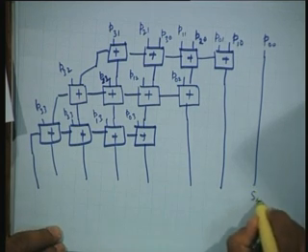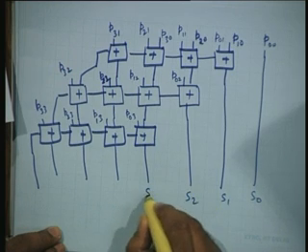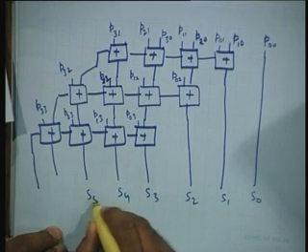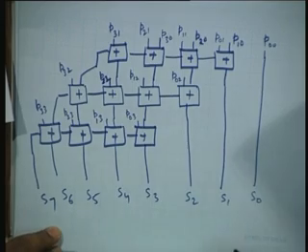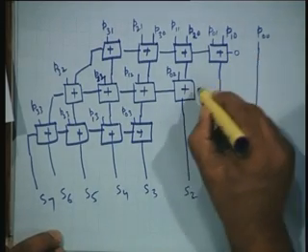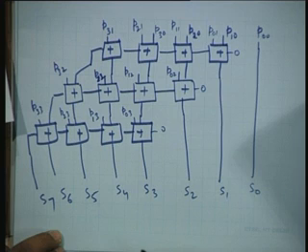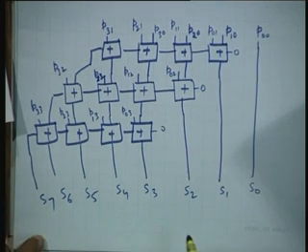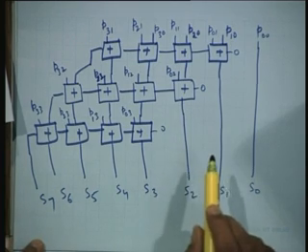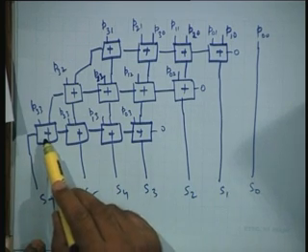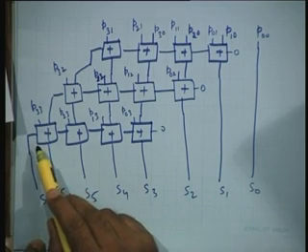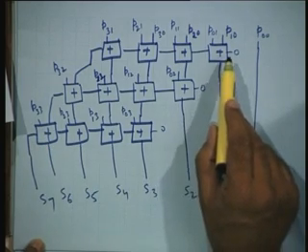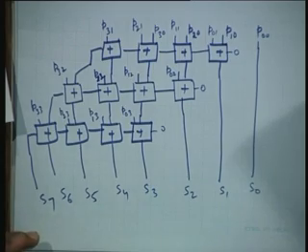Let me call these S0, S1, S2, S3, S4, S5, S6 and S7. Right. These initial carries are 0. So, we have this with normal carry ripple through. And you can see that the delay of this circuit would again be dictated by the paths leading to the S7 output, and the longest path would be this. Let me trace it out.